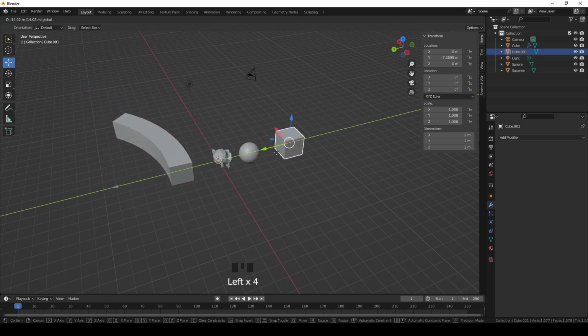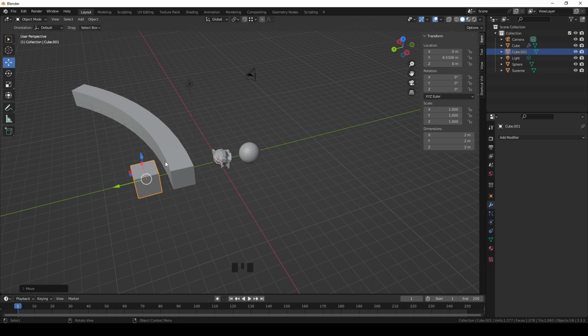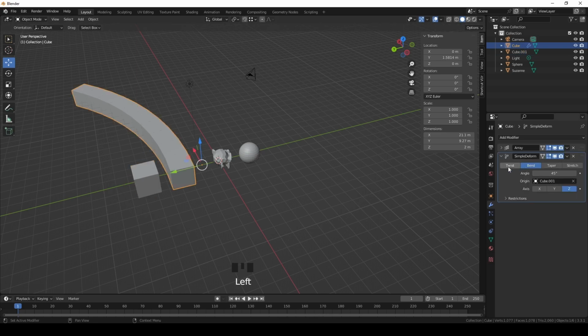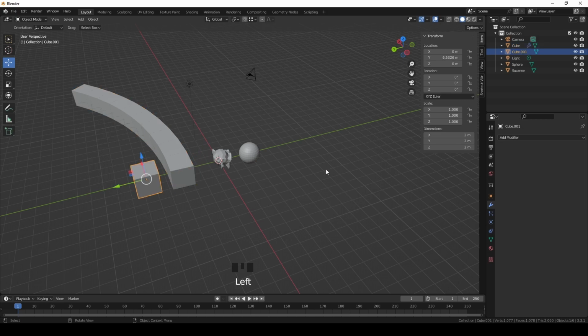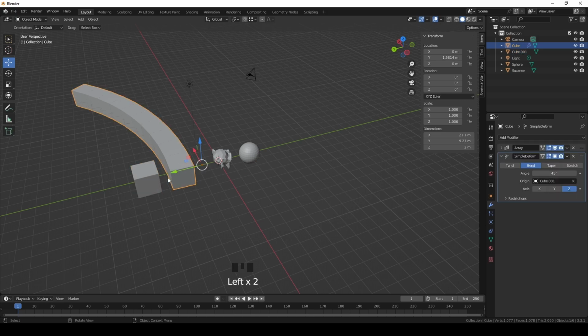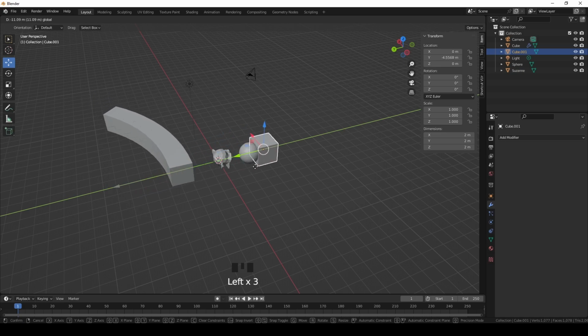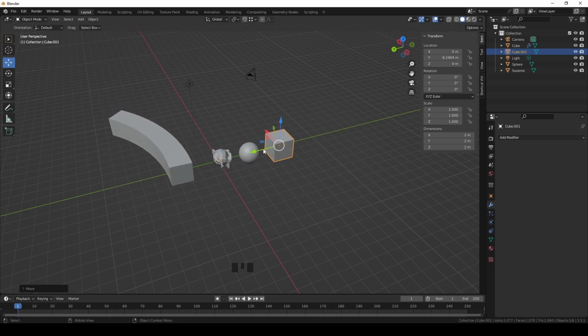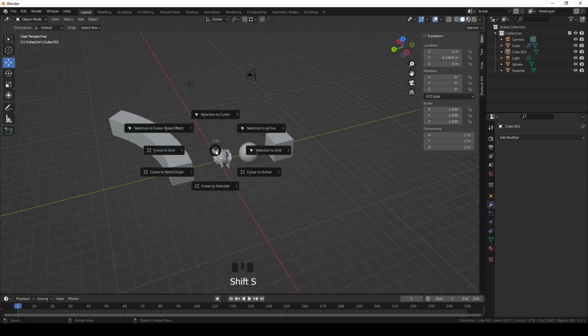Okay, if I make any kind of this movement, I can see my whole object is modified. Please be careful using this type of origin, and you have to learn these things. Okay, this is the object origin point, and we can change whatever we want. Also we have a 3D cursor. Let's look for the 3D cursor options in here. I'm just using Shift S again. Let's find the snap pie menu to see our cursor and selection options and what they do.